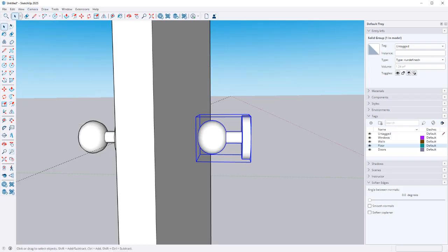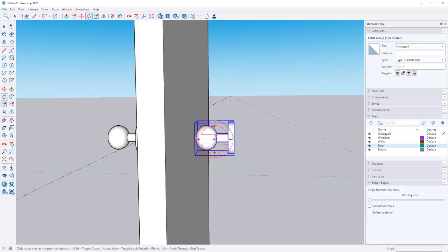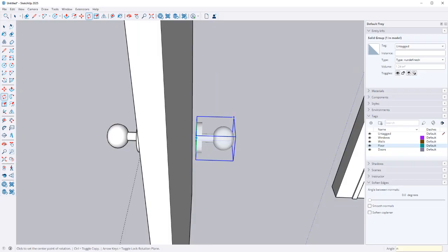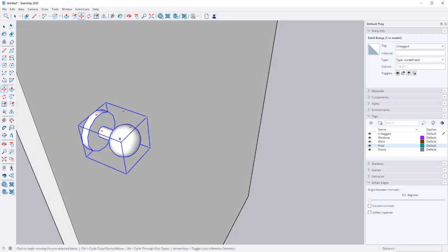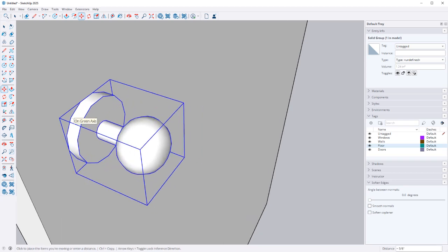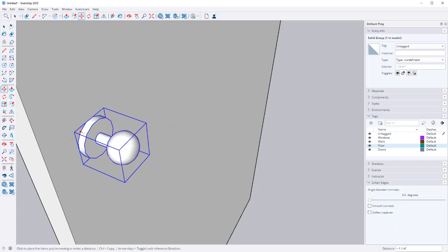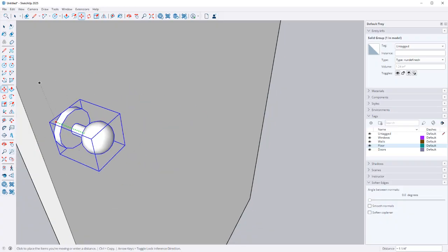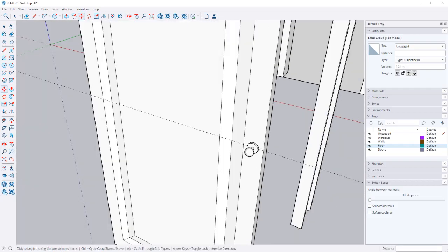Okay, then let's just grab this right here. If I hover over this little plus thing, it should just let me do that. That's probably an easier way to do it. And then I can move again. What I'll do is I'll reference one of these. So again, I stressed in AutoCAD, grab things by the things you can snap them to other things with. So I'm going to grab the face of this right here. I'm going to start moving it off in that direction, hold down Shift, and then move my mouse onto the face right here, and it's going to get that completely flush with the door.